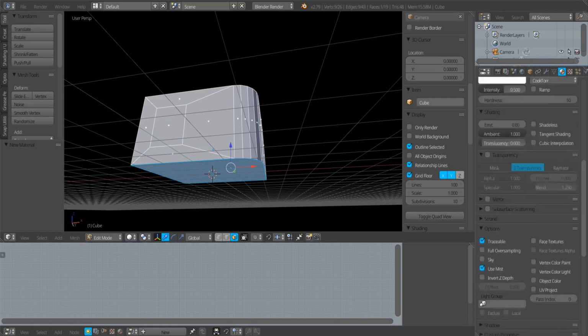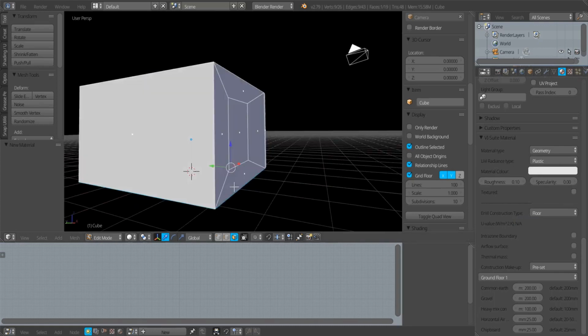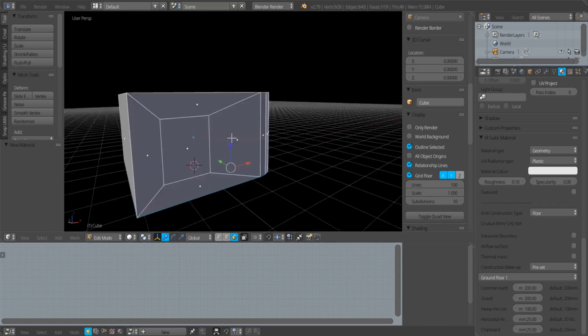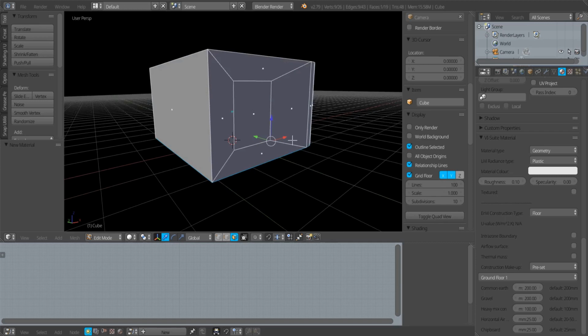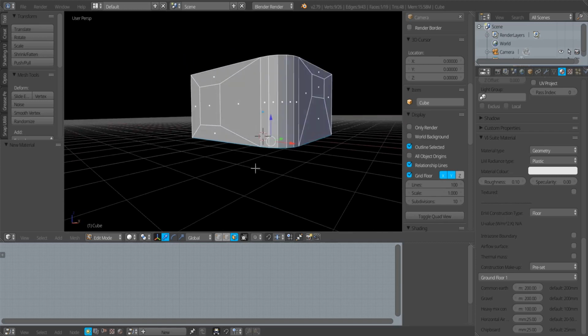That's now the floor done. Now I'll say something about the floor while I'm here. The V-Suite, when you have something designated as a floor, or in fact when you have any surface within a zone, within a Blender object, any surface, if its midpoint is below the ground plane in Blender, or the z=0 plane in Blender, it will assume that the outside boundary condition is the ground.